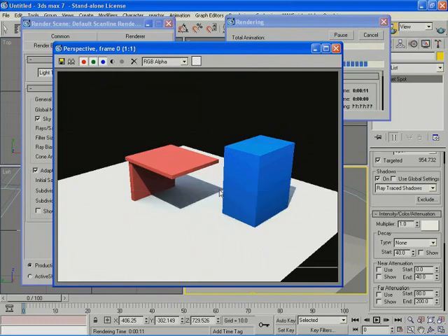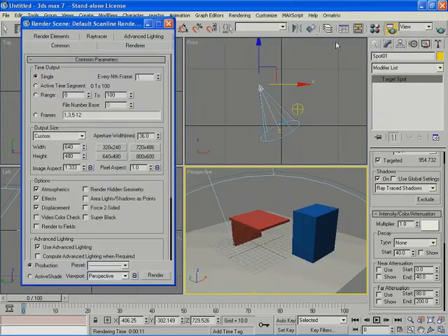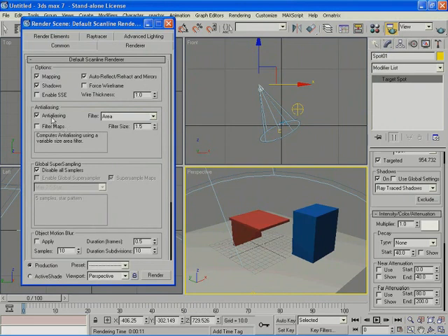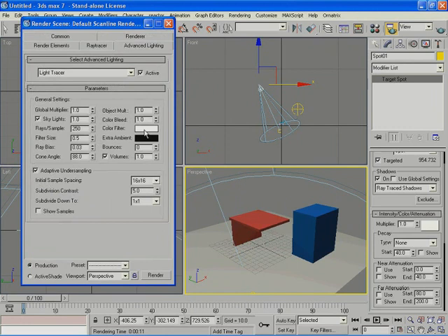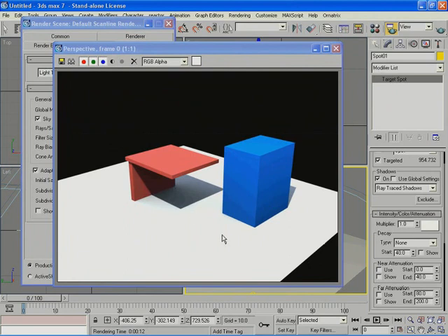All right, so so far I don't have a lot of color bleeding. And this is coming from the fact that color bleeding comes from light bounces. So there's my light source down here, up here. It comes here, and it's going to hit that surface, and then it's going to bounce back. So in case I don't have any bouncing, I'm not going to have any color bleeding. To get color bleeding, you need to activate bouncing. And by default, bouncing is set to 0. So you have 0 bounces, and therefore you have no color bleeds.